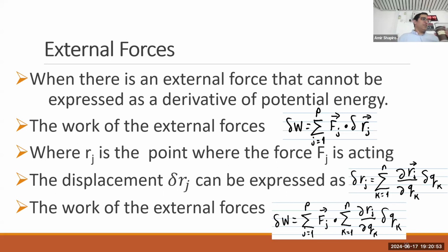When there is an external force that cannot be expressed as a derivative of a potential function, of a potential energy, the work of external forces is simply the force times the displacement, delta R, where Rj is the point where the force Fj is applied.